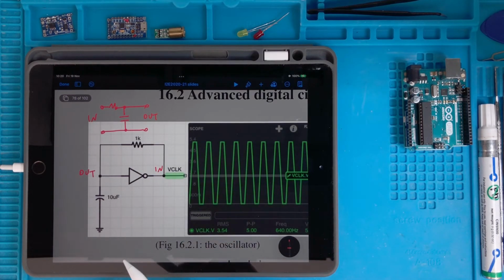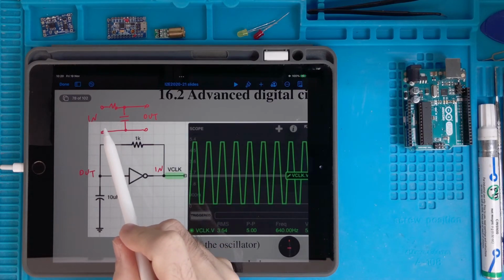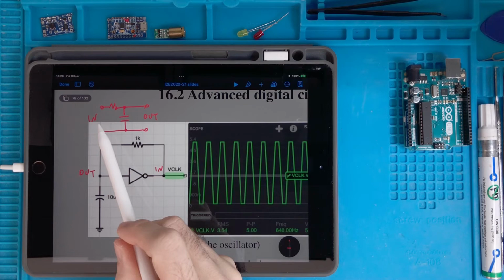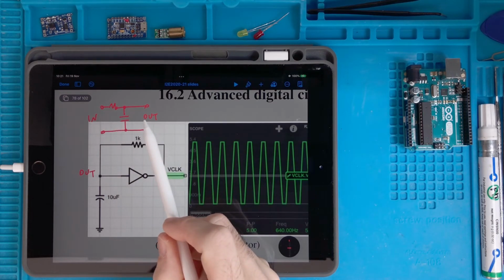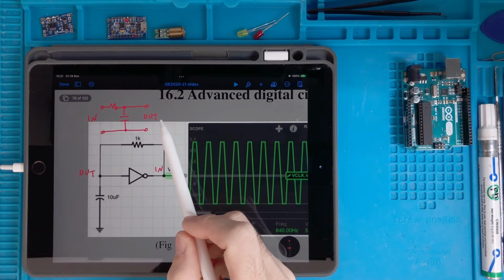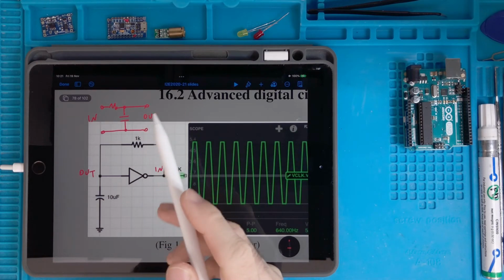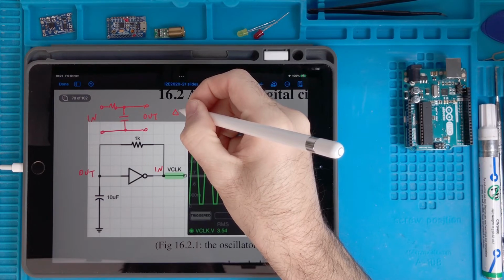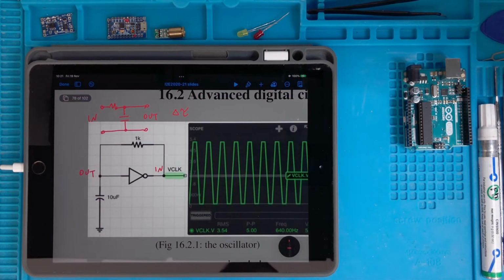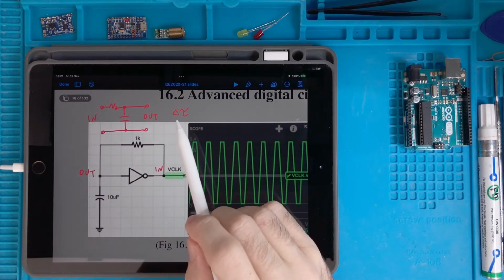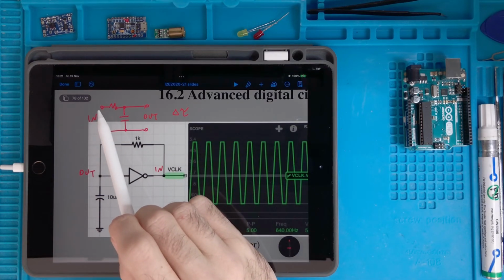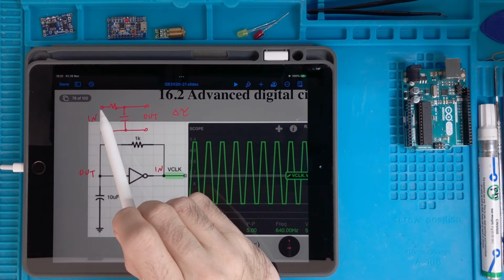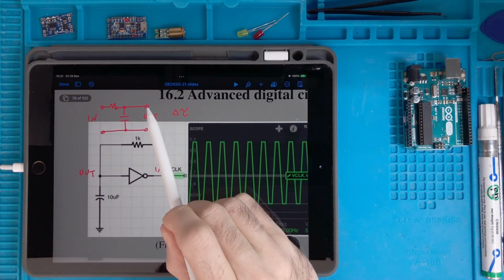This is one of the times where the phase is important. This circuit does not only create a modification on the amplitude, but also on the phase, which means that it will create a delay. So there is a delta t, a time that passes from the moment you apply a signal here to the moment you have it at the output.